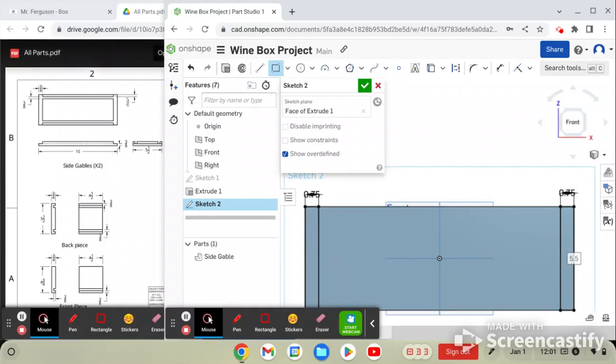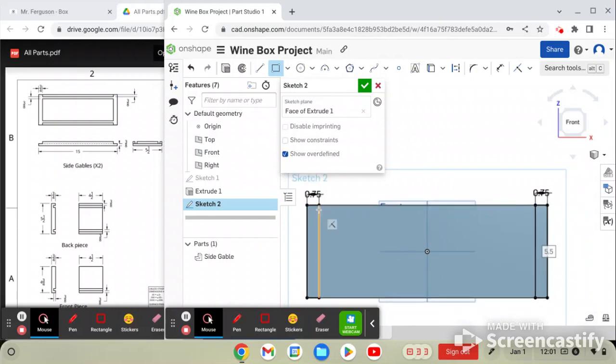Now we want to do the dado joints in the middle. So let's create our corner rectangle. We have that selected. And as you can see, it says it's 3/8 of an inch for the top part and 3/8 of an inch for the bottom part. Those two combined are 3/4 of an inch. So I'll just select the corner of our first rabbet joint,